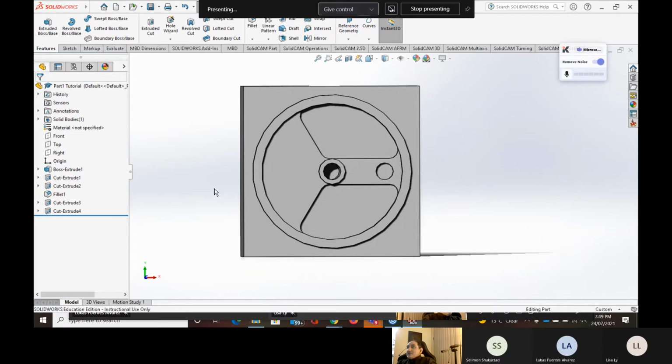The time required to do the 3D printing is quite long, too long. That's number one. Number two is that the property of the material is not going to be as strong as the one we're going to have from machining. The main properties problem we have is, if you can melt something with a 3D printing machine, that means it's not going to be able to take the high temperature in real life.